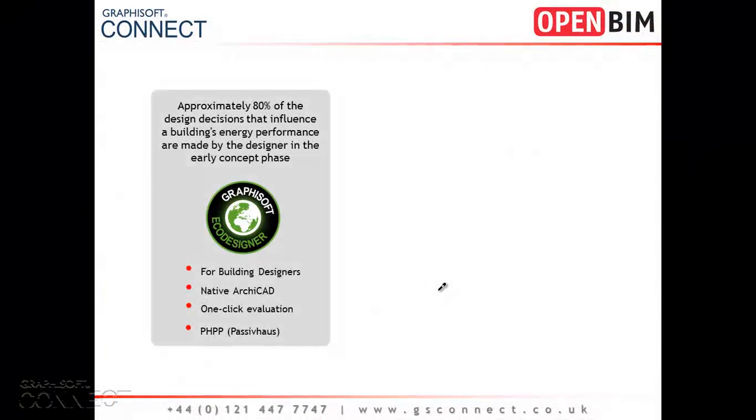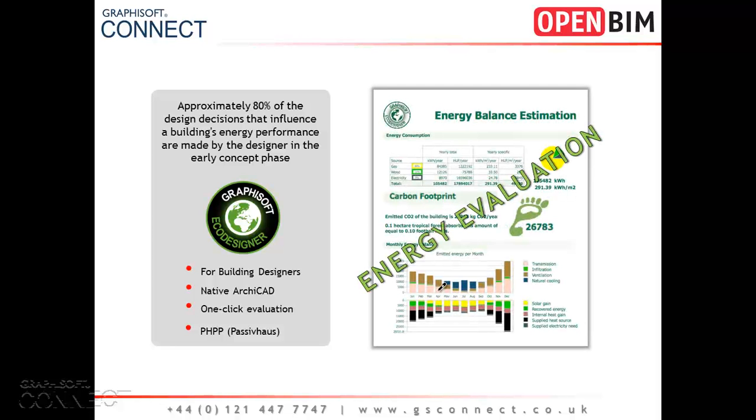The next part of the suite to discuss is the energy evaluation, which is built in to ArchiCAD 16. This is fully embedded in the system. It's designed for building designers. You don't have to be any sort of energy evaluation specialist to understand the results. It works natively inside ArchiCAD. It's very simple, sort of one click. Once you have the model you can analyse it, and it also exports to PHPP for further analysis in Passive